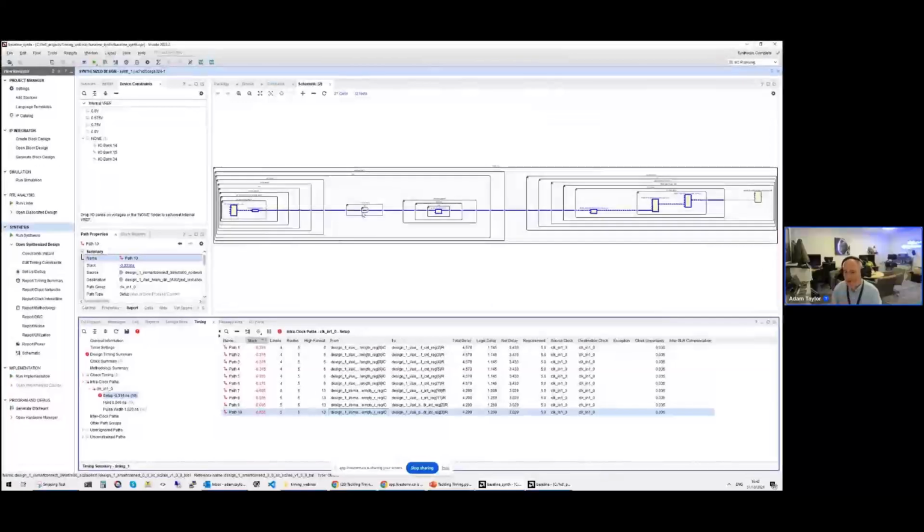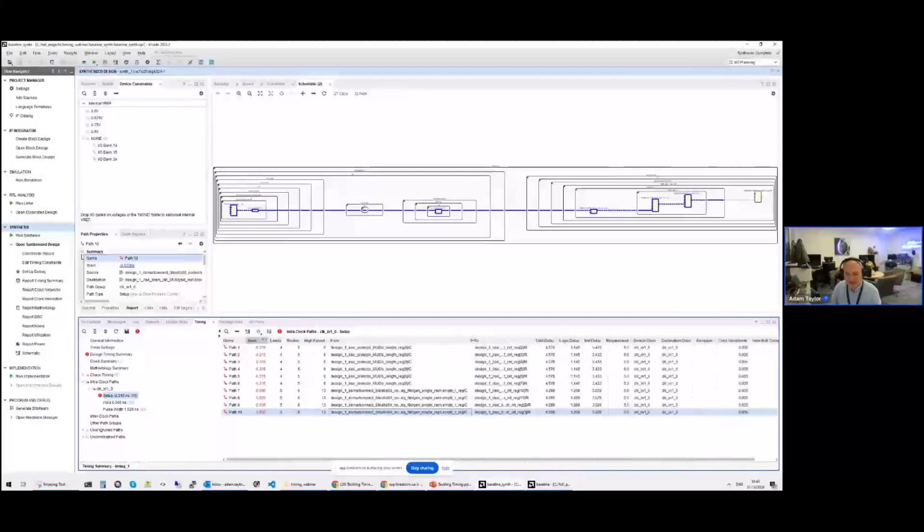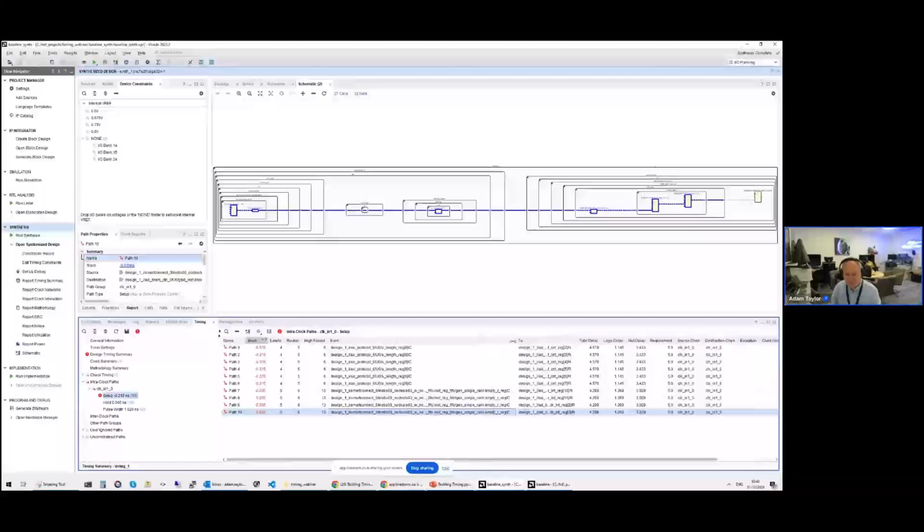If we do that, we can open the timing constraints. We can run the timing estimation, timing report, and we will see that we have 10 failing paths here. And these paths are related to the Smart Connect to the block RAM and something within my RTL. Perfect. Couldn't have timed this any better for an example.